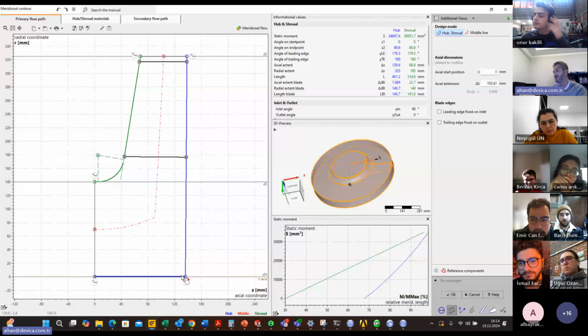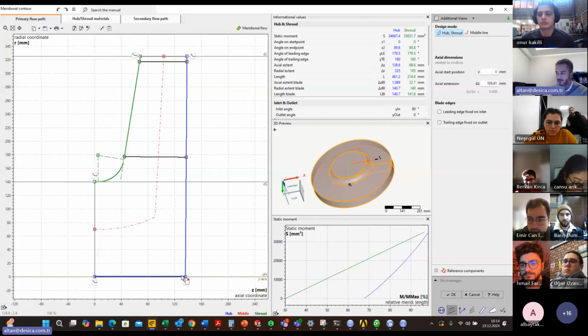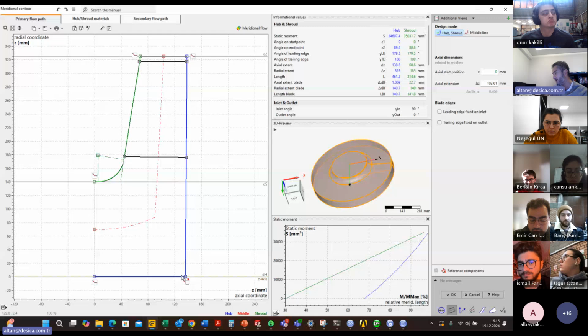Since it's left over from the artificial hub, I defined an artificial hub for the single blade simulation, but I converted to the full stage because Kahraman Hoca is expecting the volute simulation as well. That's why single blade simulation is not a case for the centrifugal fan. As for the axial pump or axial fan, you can still use the single blade solution. Okay.